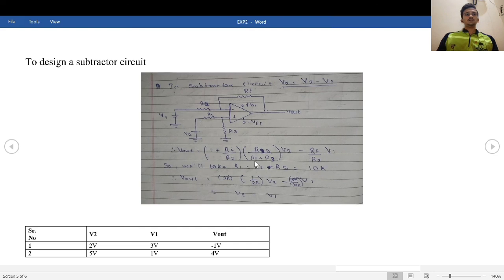So we'll take resistors as R1 is equal to R2 is equal to R3 is equal to 10K. So this combination becomes 2. This combination becomes 1 by 2. So 2 gets cancelled. So this becomes 1 into V2 minus, and 10K by 10K is also 1, so V1. So our final output equation is V2 minus V1, which is nothing but a subtractor circuit. So we'll also check it for different combinations.